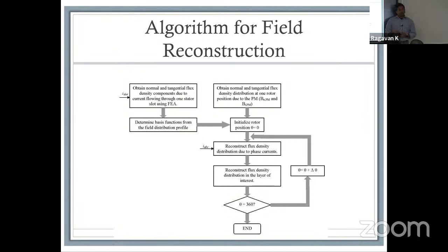What this does very quickly for you is let you define the optimal current for your system. If you know what you're trying to optimize for, such as maximum torque or minimum radial force, depending on the application, you can define what the current is supposed to be.